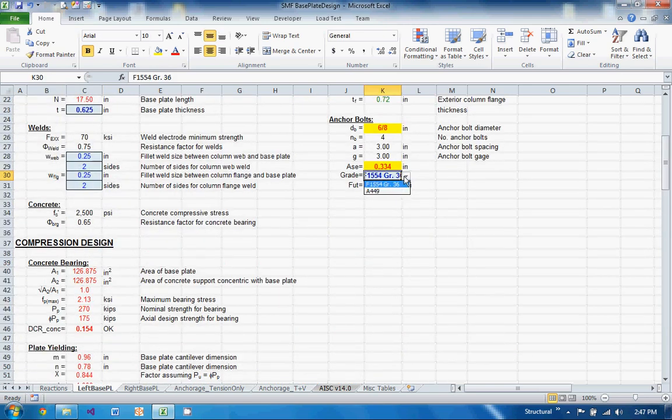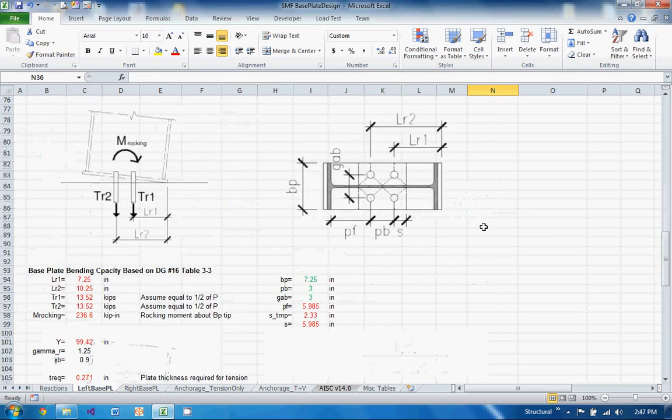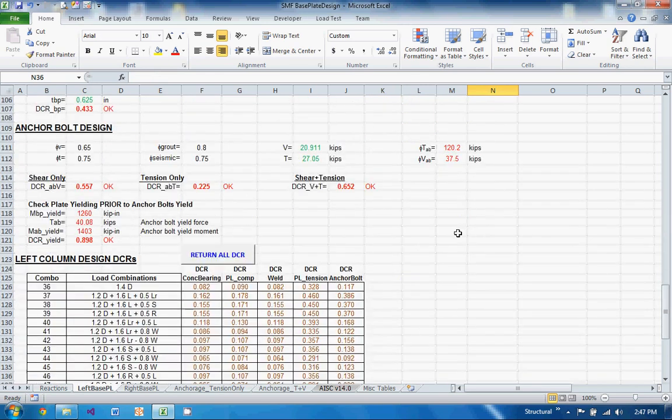This is just our self-imposed requirement, it's not in the code. But if you have to replace something, it should be the plate that's outside, rather than digging out the concrete to replace the bolt.